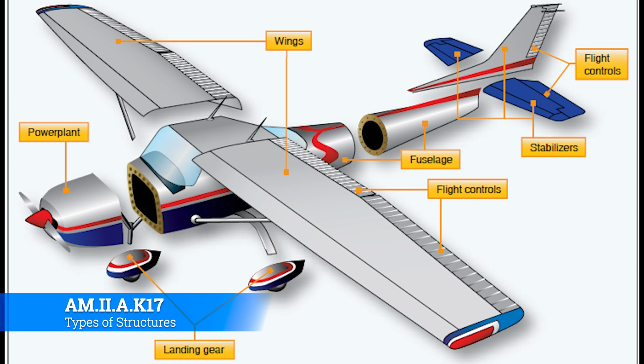So the power plant, we're just going to start at the graphic and work our way across from left to right. The power plant is the fancy way to say aircraft engine. A power plant can be a turboprop, turboshaft, a turbine engine of any variety, a reciprocating engine, even electric engines. Those are all power plants. Oftentimes, almost all the time, the propeller gets lumped into the power plant nomenclature as well. So whenever we study props, it'll be in power plant, because that's what goes on the end of an engine, effectively.